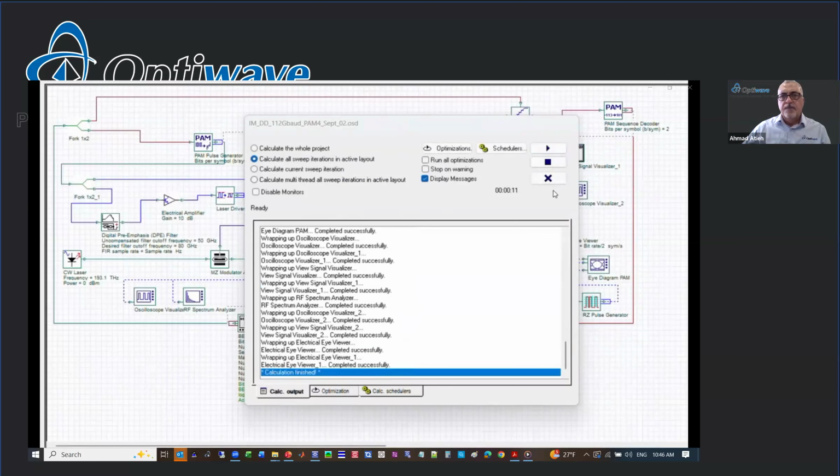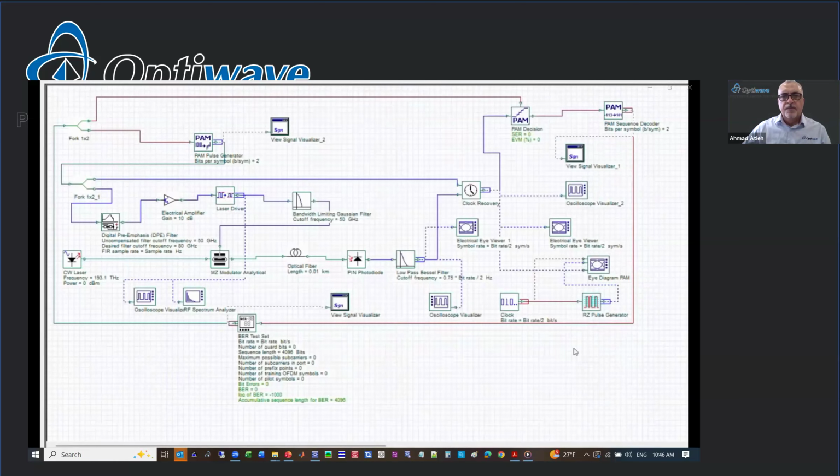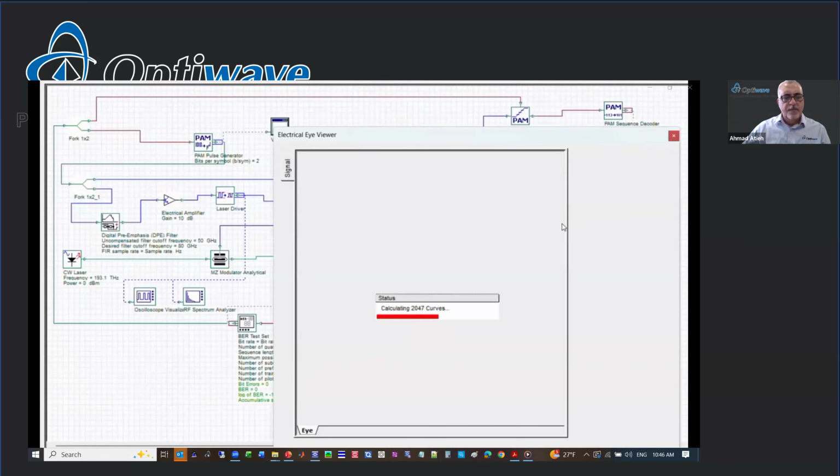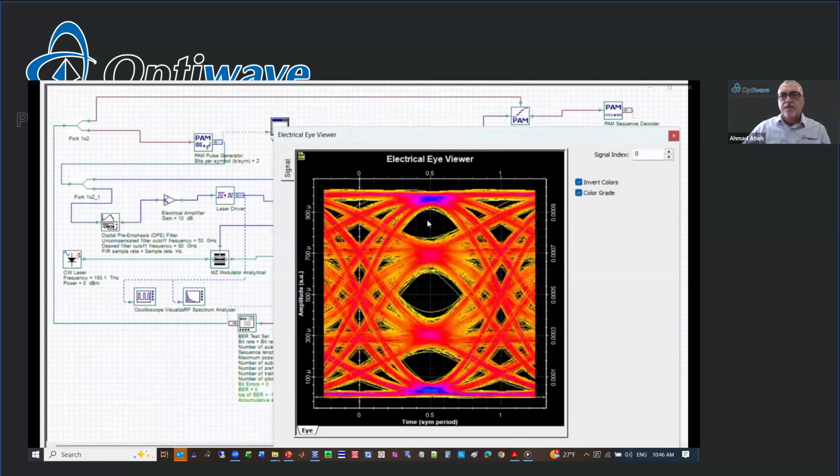And you can see here that you also have error-free operation with digital implementation, and your eye diagram is error-free. It's not as good as the analog implementation we did initially, as there are always some effects due to truncation, windowing, and the finite resolution of the taps in the FIR coefficients.